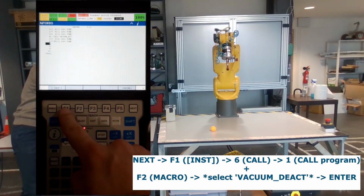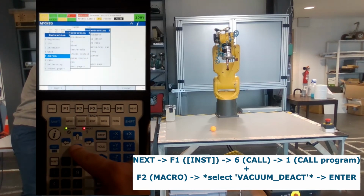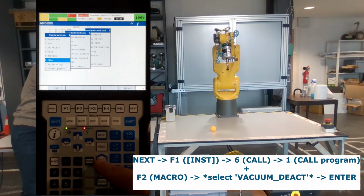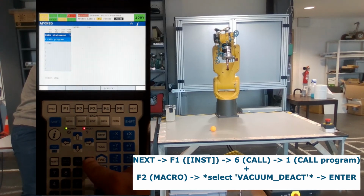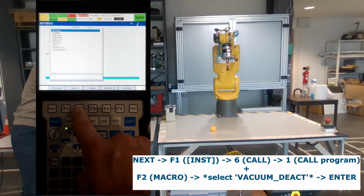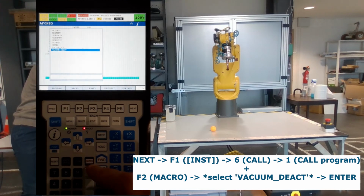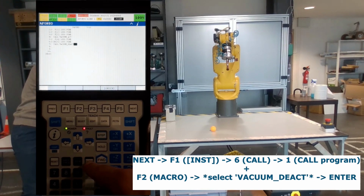Now, for the final script line of our program, we want the robot to release the ball. For that, I will call the macro program to deactivate the vacuum. Press the next key, then F1, the call and then call program. Choose the macro option on the F2 key and select the vacuum_deact by pressing enter on it.